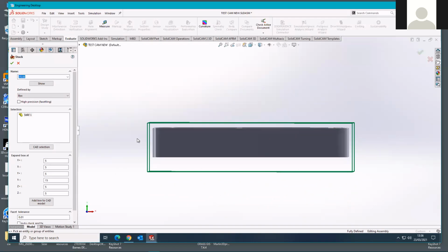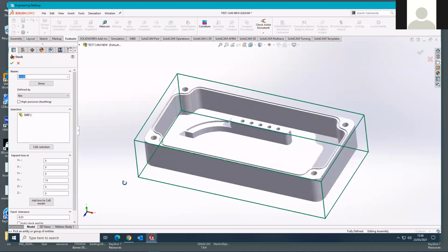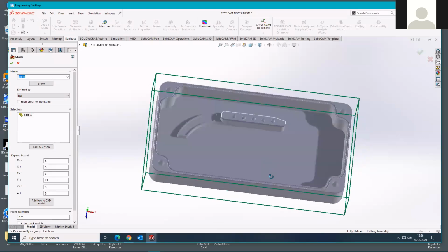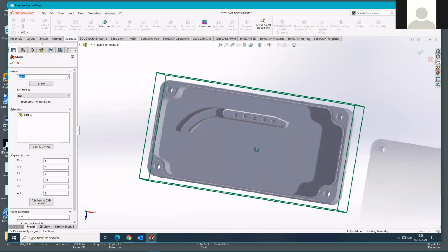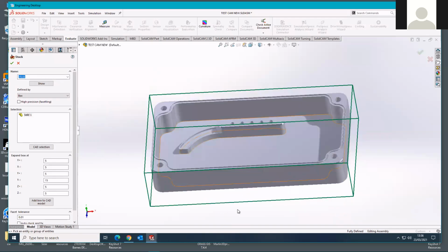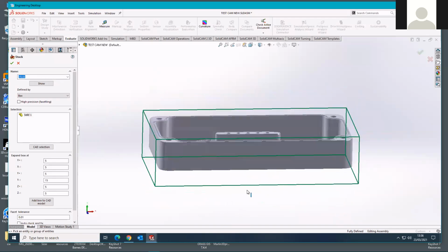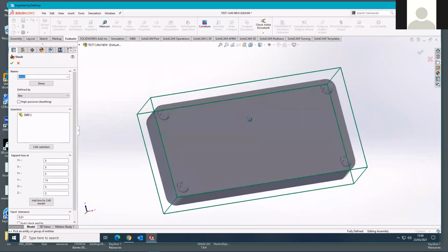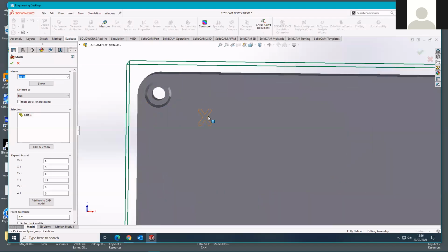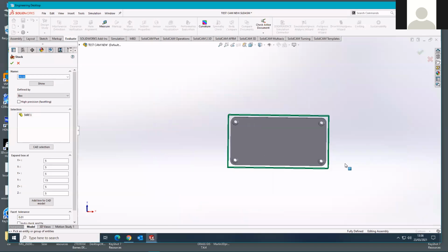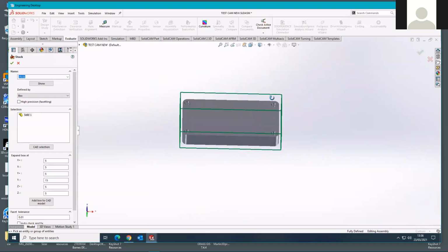And then when we get a little bit later on in this exercise, probably next week, and we've created all this geometry on this side of the box, we then create a second setup where the CNC machine operator would unclamp the box, flip the box over so that the machine is now approaching it from this side, and then we could address these through holes and these counterbores and the engraved X, which is on this side as well. And again, we'd have to come up with some method of clamping it.